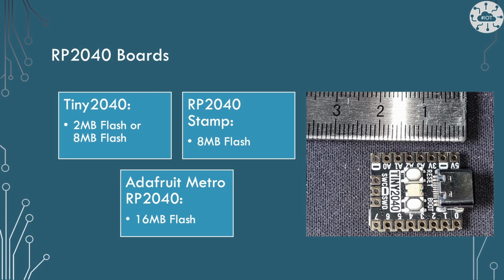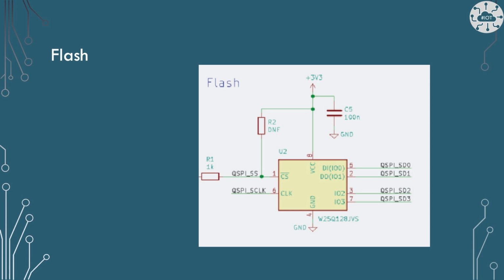So actually, flash for storing these things is readily available, and we can find some quite bigger boards out there to use for this. They do this because the flash is actually not on the RP2040 core, the actual processor that the Raspberry Pico uses. It's actually a separate chip and communicates via SPI.